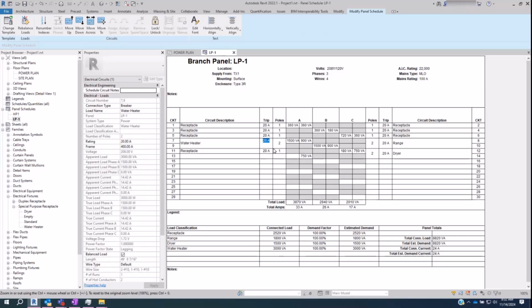Now, when you get into larger stuff, this minor side note, by the way, like 800 amp breaker and above, you can't just jump to the next size breaker because that's just too much. But any branch stuff like this, yes, next size up, totally fine. And prove it. Whenever you put in 15, it tells me, hey, you need to be aware this is exceeding 80% of the defined rating. So it's telling me I've got a problem, my breaker's too small. But it doesn't tell me that whenever I've got 20.